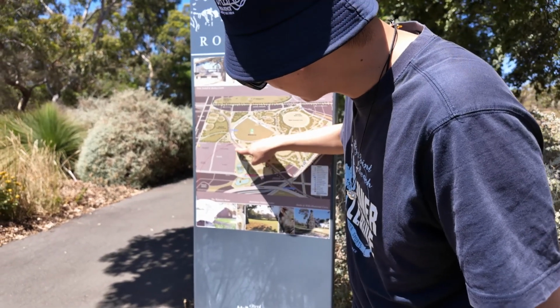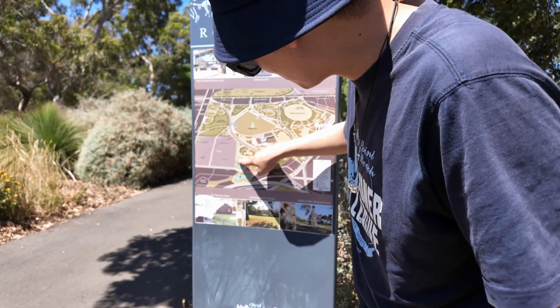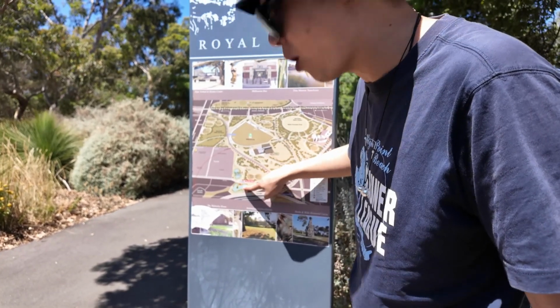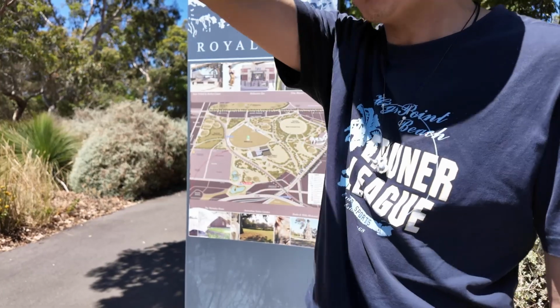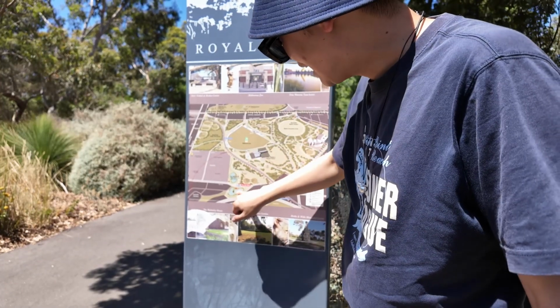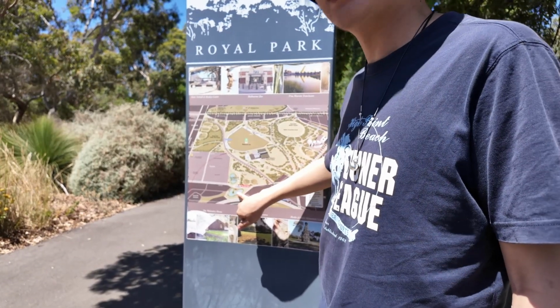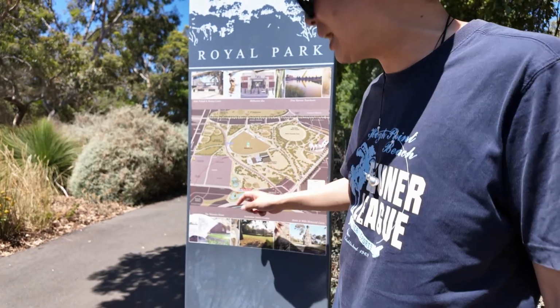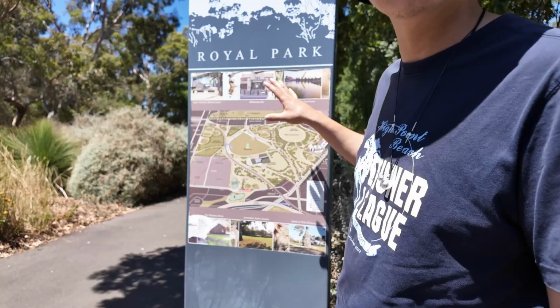So we divert water from this creek and treat that water in this wetland. And then the clean water is stored in this pond, which is across the strip. The road will take you there. And this is called stage 1 of the project. So from that point, water is treated by UV disinfection and supplied for the park.